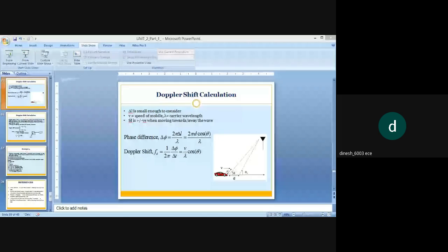Then we need to compute the receiver carrier frequency if the mobile is moving towards the transmitter, and directly away from the transmitter. Then we need to find it in a direction perpendicular to the direction of arrival of the transmitted signal. That means there is no Doppler shift in that case.